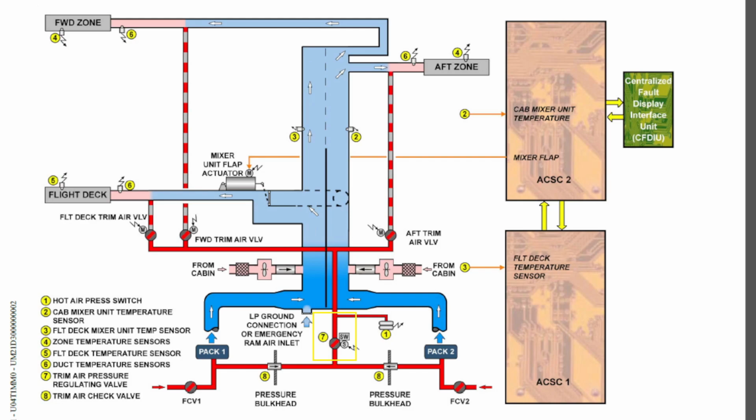And you have to remember another thing, this is a pneumatically operated, electrically controlled valve. Which means even though the valve is controlled to open using the solenoid by electrical power, you still need pneumatic pressure upstream of the valve to open it. It will be kept in the closed position by a spring. When you have the required amount of pressure upstream of the valve, only then will the valve open and allow the hot air to flow into the system.